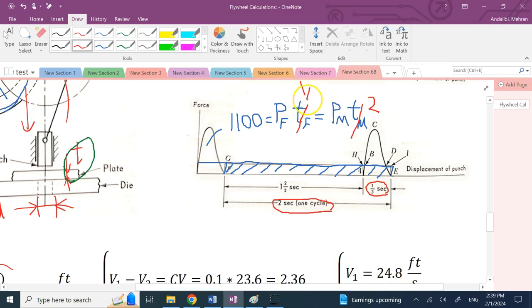So clearly you see that the power of the motor is going to be 1/6 of the power of the flywheel at any point, at this peak, right? So during the punching operation, the motor will inject this much of energy into the system, just this small triangle, this guy here.